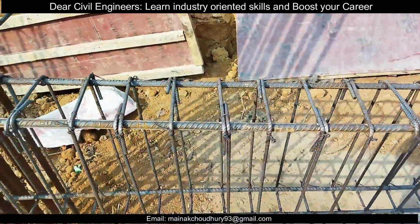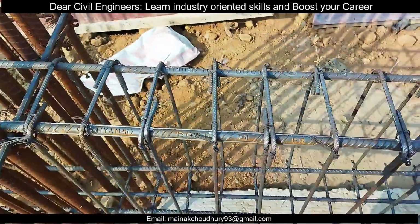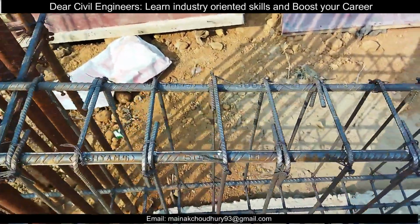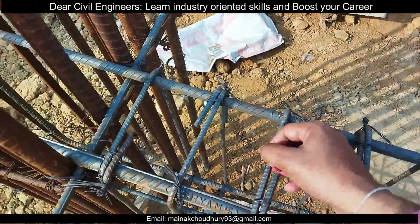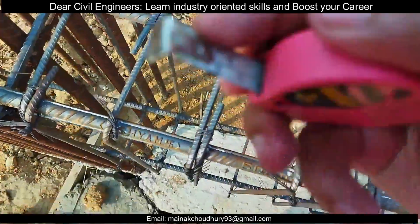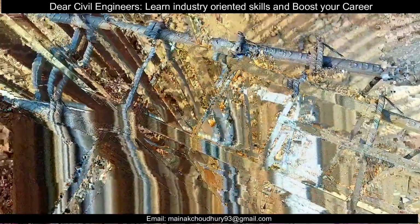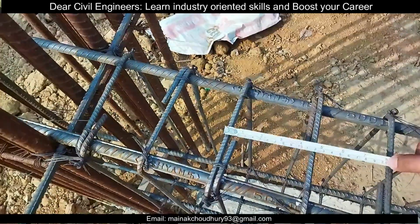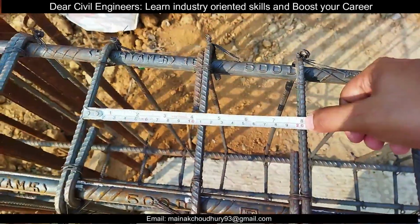The next thing is the spacing between the 2 stirrups, which you can check here. As you can see, the center to center distance of the stirrups was 200 mm. So you can check here from one particular rebar to another particular rebar. Let's check 2 rebars here. If you check center to center between these 2, as you can see, it is 200.